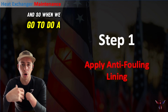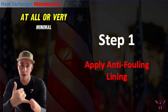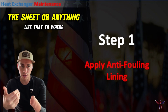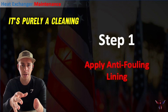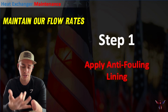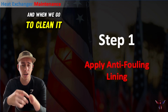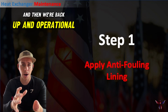And so when we go to do a service on the heat exchanger, one, we may just have no buildup at all or very minimal, something we can wipe down, or two, we can clean it with relative ease, but we didn't affect the underlying material, the sheet or anything like that, to where we don't have any actual repairs to make. It's purely a cleaning. That's one of the big benefits of the anti-fouling: we maintain our flow rates, we keep our heat transfer rates high, or within range of what they should be, and when we go to clean it, all we have to do is clean it. We don't have to clean it and then fix it. It's just a cleaning, and then we're back up and operational.